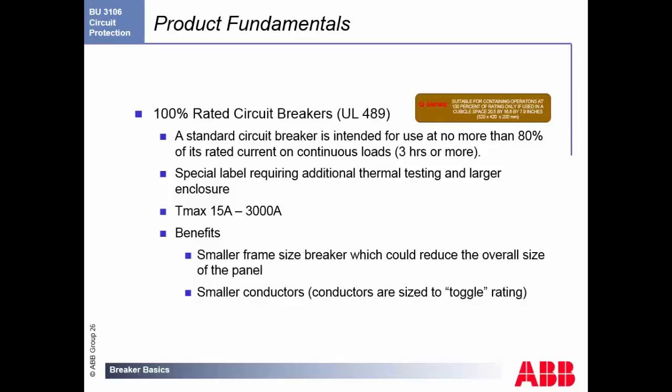It's unique, which means you can control the loads, which is typically not an application that's recommended for opening and closing that load. So generally, I know it's not the right application, but a lot of people, as they leave their building for the weekend, want to flip one switch and have everything shut down. These circuit breakers can handle that. It is intended for no more than 80% of its rated current.